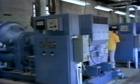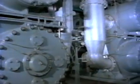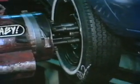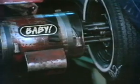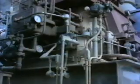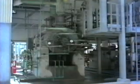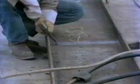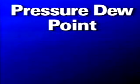When considering the capacity of a compressor, do not confuse pressure and volume. Both airflow and air pressure are required to do work at the point of use. It is vital that all those involved in the design and purchase of compressed air equipment agree on the operating conditions that the equipment will face. This will avoid frustrations later.